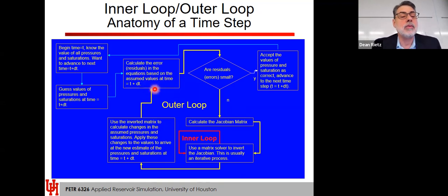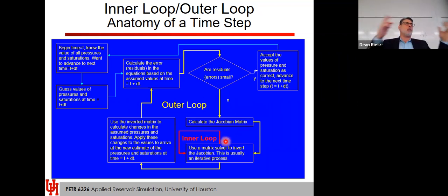What we do is calculate the error of the residuals, and then we ask, are they small enough? And we move on. That will keep feeding on itself until you get it smaller. Correct. And sometimes you might never solve. So sometimes you'll get a message that you have an inner loop error, and some simulators call it something different. Or they'll say it wasn't able to converge. And there are some things we'll talk about, what to do with the model to help make it converge.